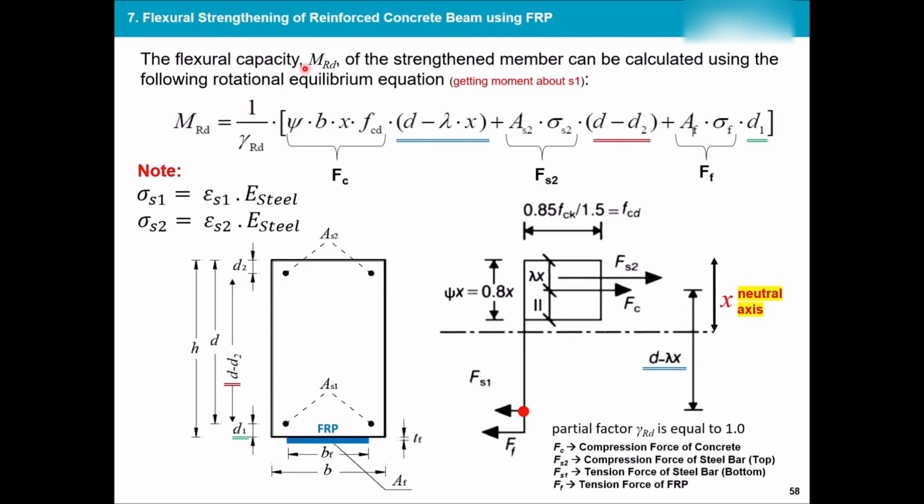So the flexural capacity, which I'm always looking for, do you remember we were saying that the flexural capacity, your resistance, should be higher than your applied? I got the applied from my analysis, from my GSA, from ETABS. I was just trying my best to calculate the resistance of my section. This is the resistance. It's just force times the distance to that point.